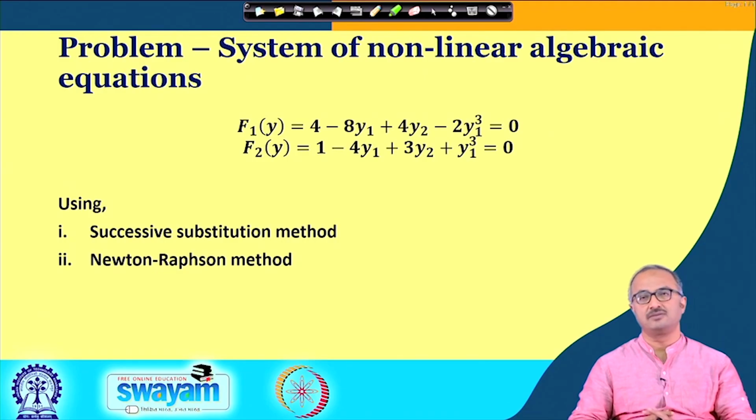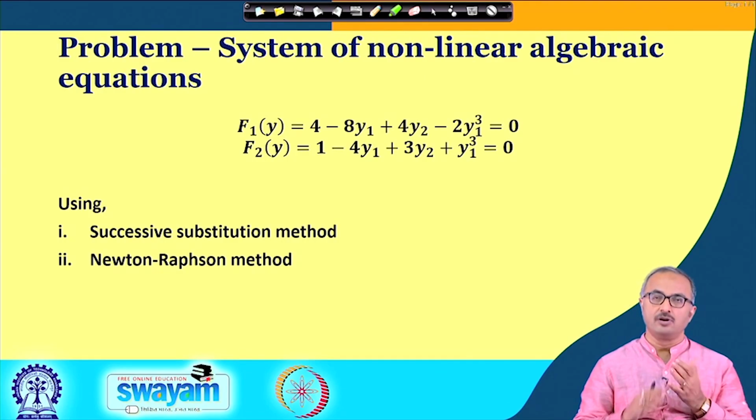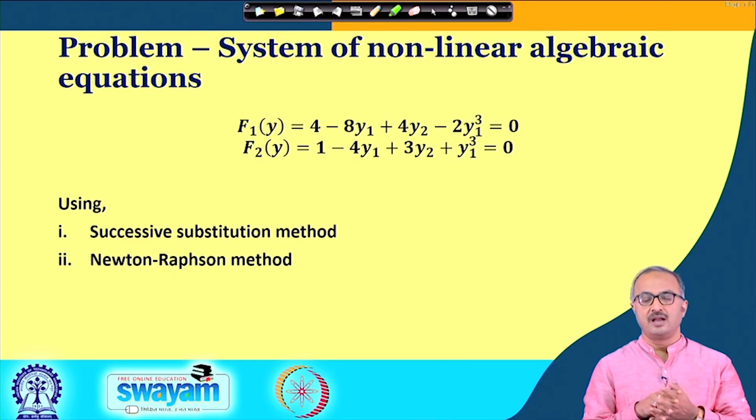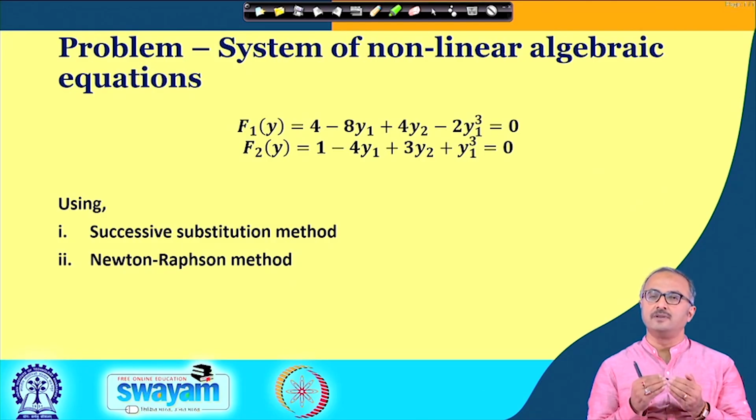What happens in those cases is that you write the balance equations for momentum transfer, mass transfer and heat transfer, and then you find that all these equations become coupled. For example, in the heat transfer you will find the velocity is coming, and the velocity is obtained from the momentum transfer, and again in the momentum balance equation you may find the various properties which you are using may be varying with the temperature.